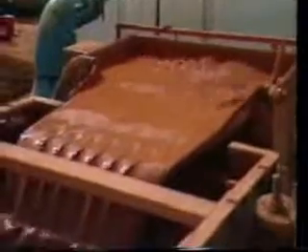The circulating mud moves through the swivel, Kelly, and drill pipe, exiting through the bit at the bottom of the hole. From here, the mud moves up the annular space between pipe and hole, carrying the drilled rock cuttings in suspension. At the surface, the mud leaves the hole through the return line and falls over a vibrating screen called the shale shaker. This device screens out the cuttings, allowing them to be sampled before being discarded.